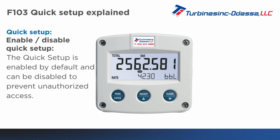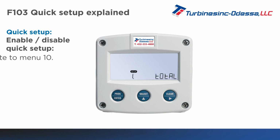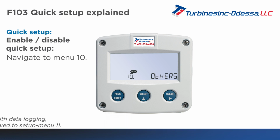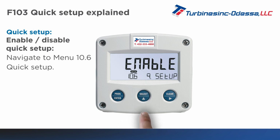The Quick Setup is enabled by default and can be disabled to prevent unauthorized access. To disable the Quick Setup, hold the Program button for 7 seconds to enter the Setup mode. Menu 1 Total appears. You can use the Prog, Clear and Select buttons to navigate through the menus. Use Prog to navigate to Menu 10 or 11 Others. Note, when the F103 is equipped with data logging, option ZL, Setup Menu 10 Others is moved to Setup Menu 11. Use Select to go to Menu 10.6 or 11.6 Quick Setup.